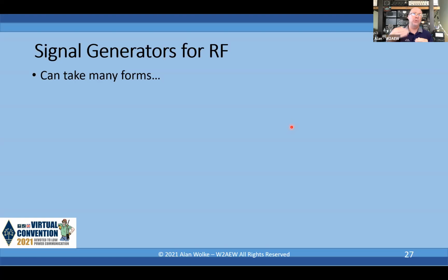As you step up to some of the more expensive VNAs, there are some that will give you the ability to do offset frequency measurements, which is what you need to measure a frequency converting device, like a mixer. Unfortunately, the nano VNA can't, as far as I know.